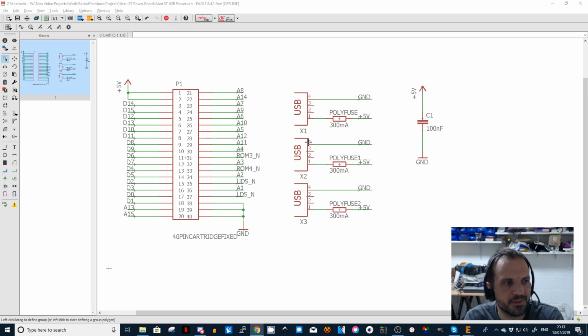I don't know. I'm lazy, Ash. I would just put some TIP121s. No, TIP121s would be massive on this. Yes, it's like 500 milliamps, Nigel. The on resistance of new FETs is so low, it'll probably be fine.